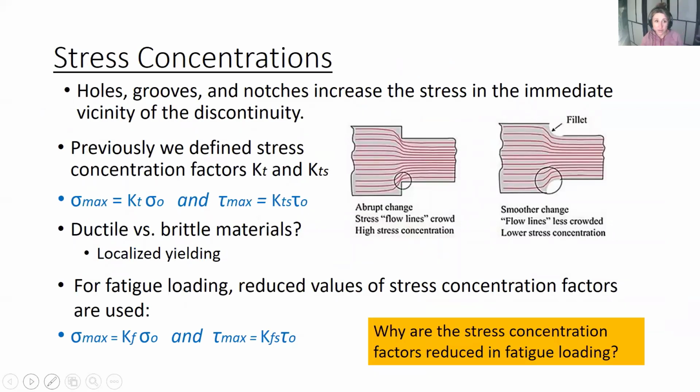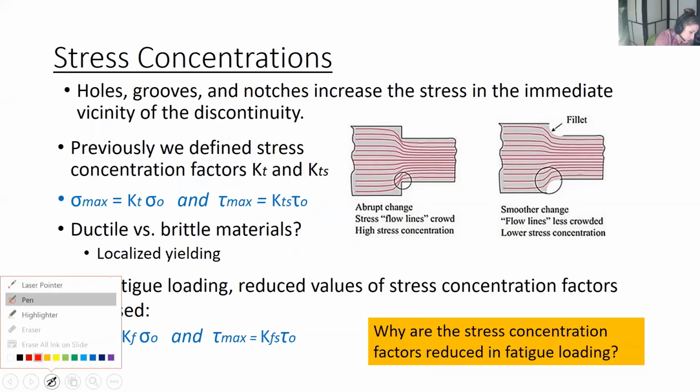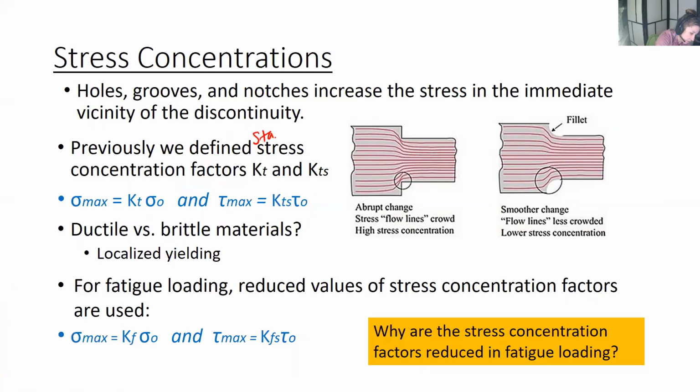And then about stress concentrations in more detail. So holes, grooves, and notches increase the stress in the immediate vicinity of the discontinuity. So in 328, we defined static stress concentration factors, KT and KTS. So the little s was when you had loading in shear.